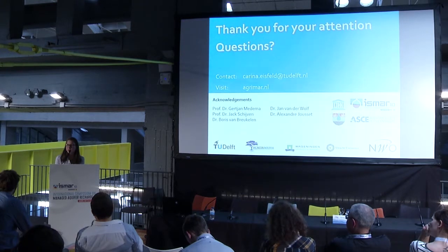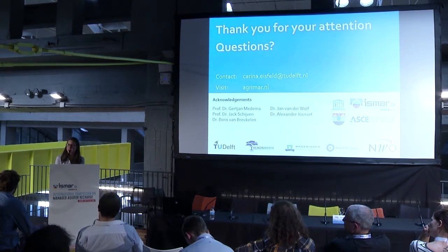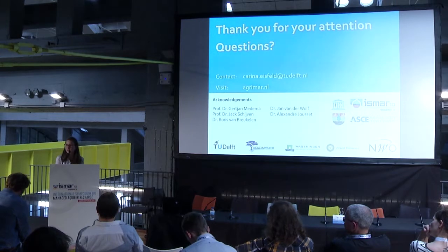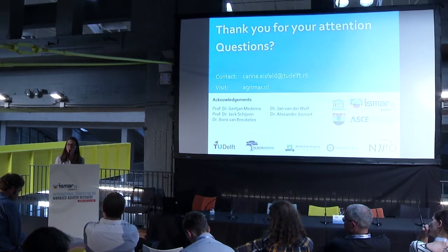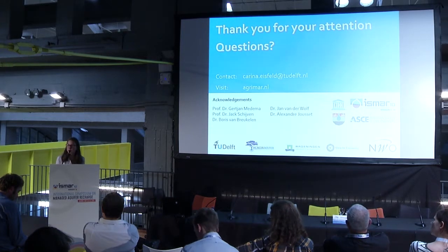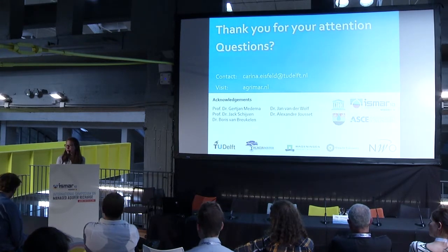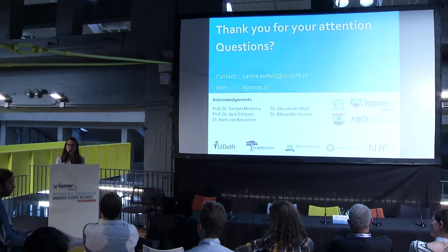For the first, I will start with very clean conditions, so I just use a clean sand, like normal quartz sand, because the aquifer where we are working is also just quartz sand with a little bit of clay added, and I will use the same grain sizes. But this is just to have really the transport parameters, because you have too many parameters if you measure everything at the beginning. But now during the drilling operations, I also collected soil from the field, and I will also use this and compare. And I will also use different flow rates, adding humic acids because organic matter competes with bacteria for attachment sites, for example, then you would have again a reduced attachment. But I just started the column now, and it's ongoing.